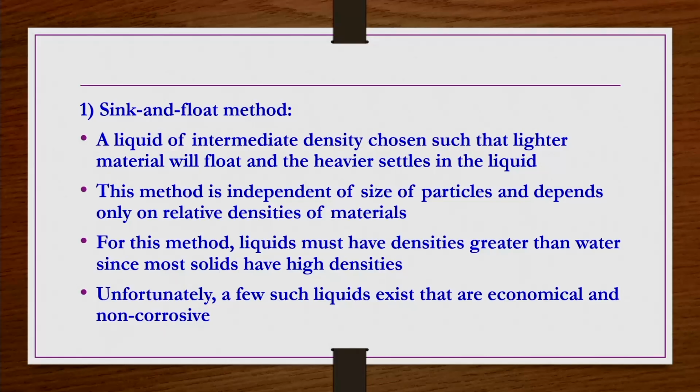That is the problem. So, though the separation is based on the density, what happens, the particles, if they have different sizes, let us say if you have a lighter particle but very big size, and then if you have a heavier material but smaller size, then it is possible that their settling velocities may be same in general.